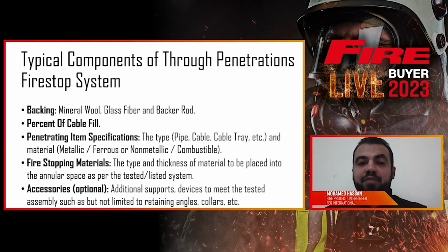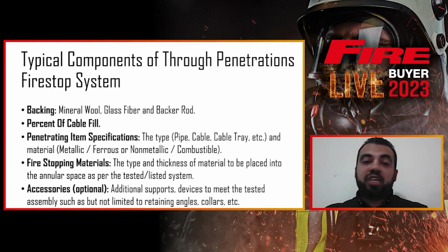Normally, the cable filling percentage is around 40%, and in rare cases goes up to 65%. So if you have a hole or opening full of cables and the percentage of filling seems very high, I believe this will not be a standard system, and you might need to go to engineering judgment or change the size of the opening.